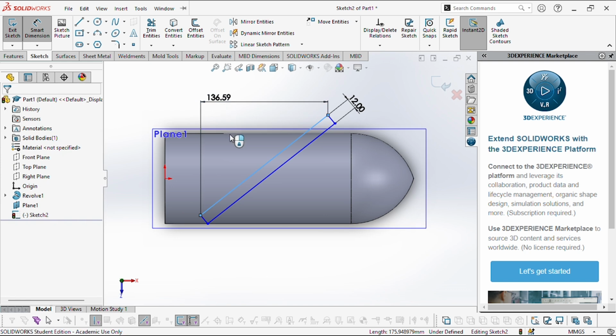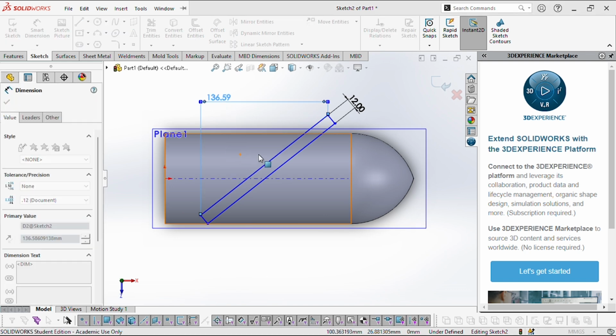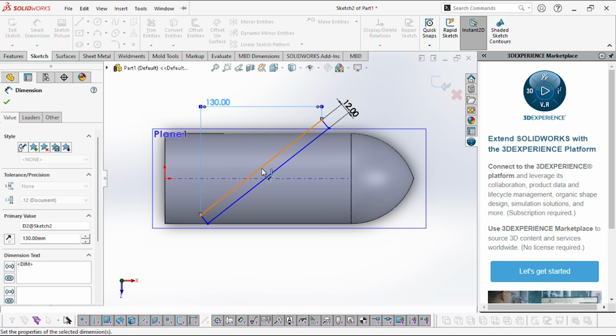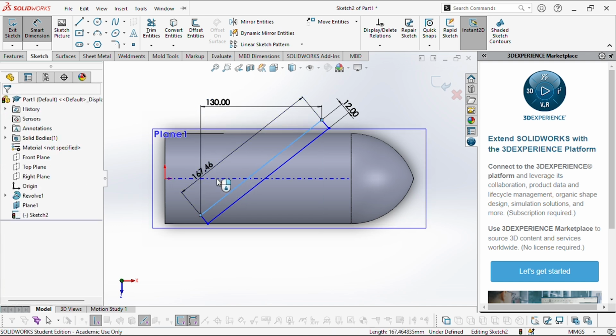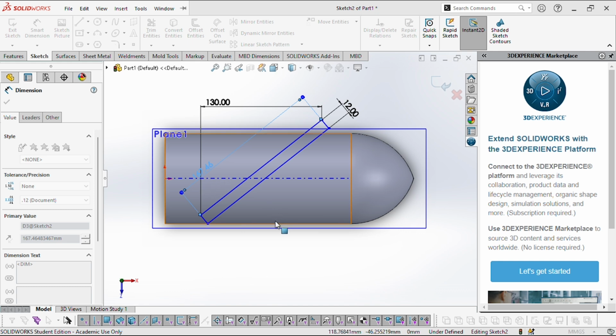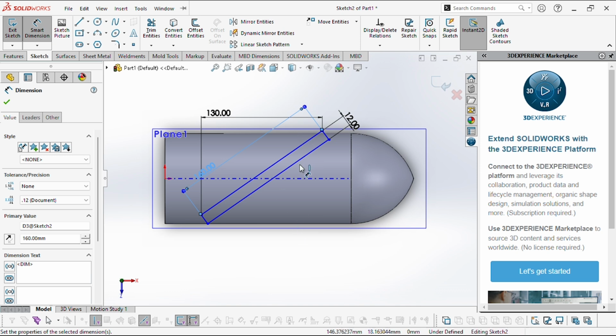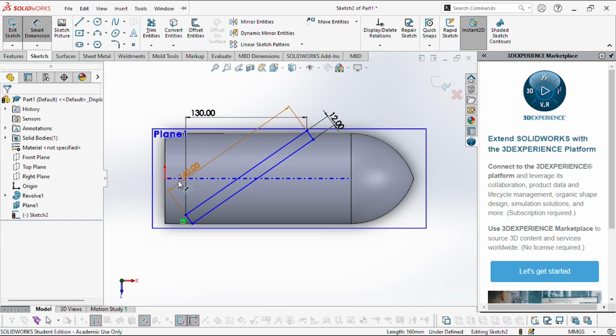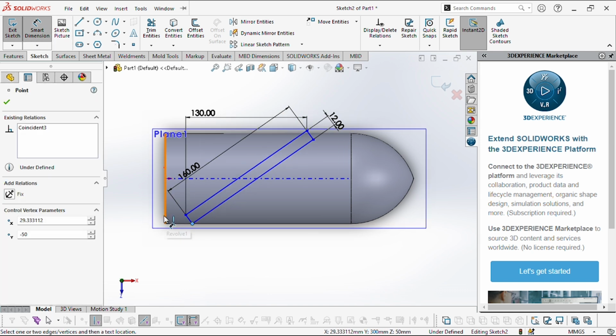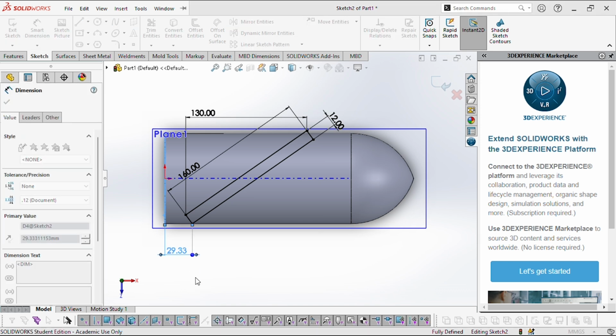So I continued designing. I designed all that, just trying to look for the best dimensions that would fit this propeller. I'm trying to fully define the sketch right now. Okay, it's still underdefined, so I was like, which dimension is left? I had to move it around to see where the constraint will be. Then I discovered it, then I had to dimension that part. Then now it is fully defined.